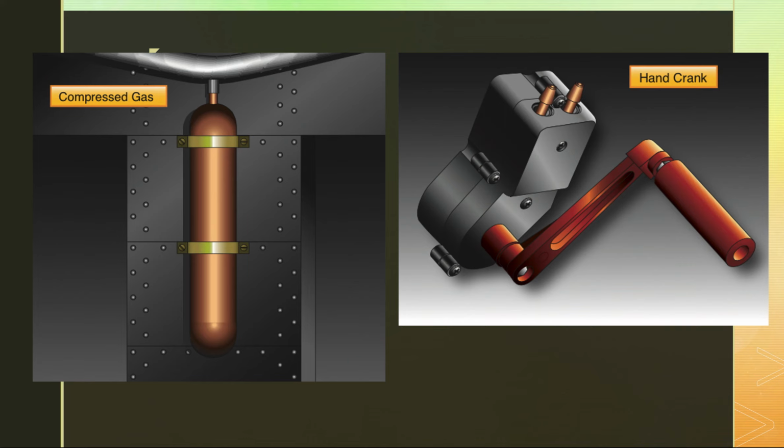And then on the aircraft that have uplocks, because the landing gear is so heavy, there's got to be some kind of compressed gas, usually some kind of nitrogen pressure or something that blows the uplock out to let the landing gear fall by gravity. In most aircraft, you need to slightly wag the nose, yaw it left or right in flight, and the wind catches those landing gear doors and pops the wheel down into the full down position. And then the mechanical down lock keeps it there.